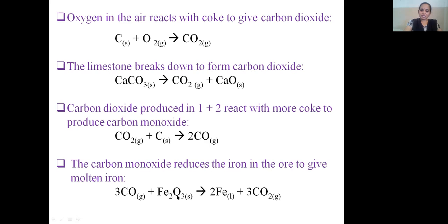Carbon monoxide reacts with iron oxide to form Fe, which is actually indirect reduction, and takes place in the stack zone. Then iron oxide reacts with carbon of coke directly in the Bosh zone, that is direct reduction. There we will find the product, molten pig iron, that percolates through the coke bed in the hearth, and from there we collect the products, molten metal and molten slag. The other gaseous products are carbon monoxide gas, carbon dioxide gas, hydrogen and nitrogen.